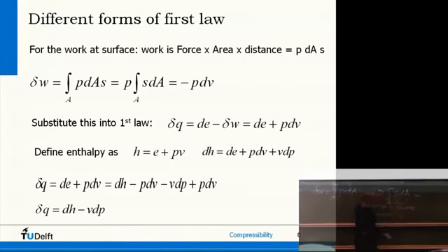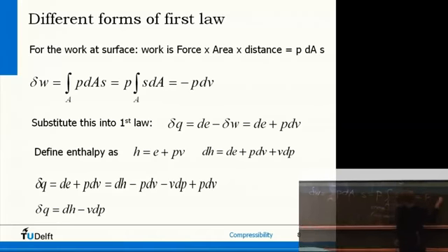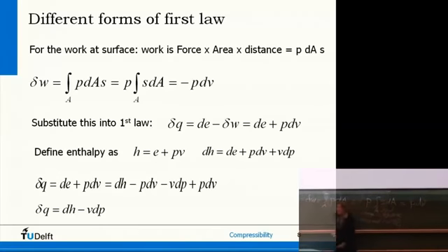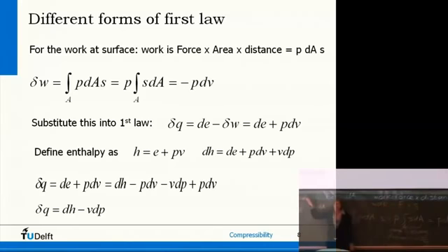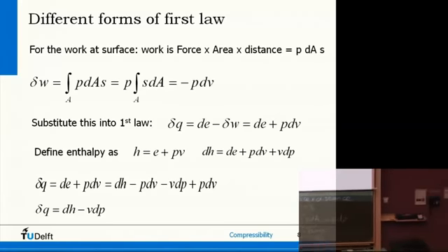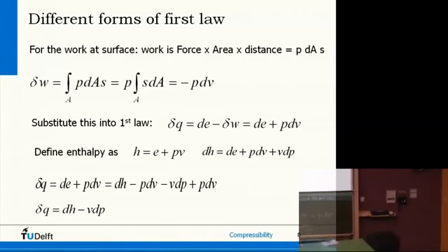So you get something that is in meters squared over kilograms, right? So you can write this as P times the specific volume I showed you yesterday, dV, the change in specific volume. And what sign should it have? Is the volume increasing or decreasing due to the higher pressure up here? It's decreasing, so it is a negative sign. So it's minus PdV. So the work done on the entire system per unit mass you can rewrite to be minus PdV, and this is the curly V, the specific volume.